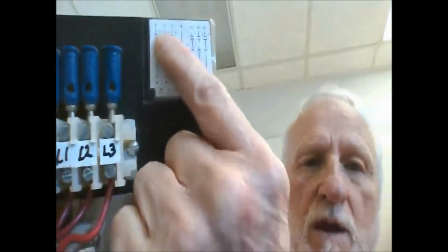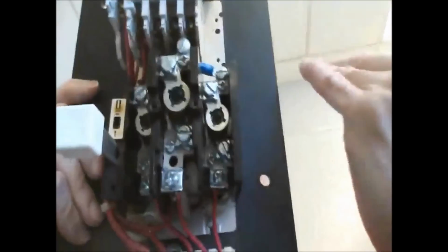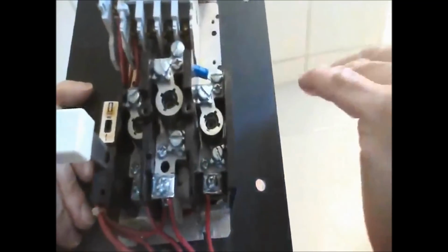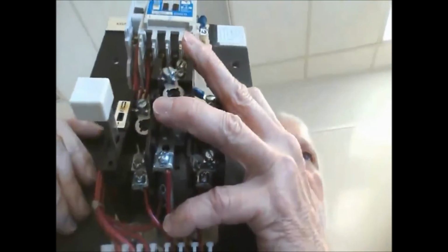And this is a normally open contact that's between numbers 5 and 6. So if I wanted to use that contact, then I would bring in a wire into number 5, and then my other wire would come out of 6. So what do the manufacturer numbers do? They show you actually how to connect the terminals on the device itself. Has nothing to do with wire numbers.